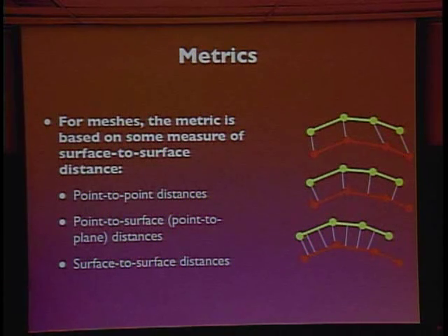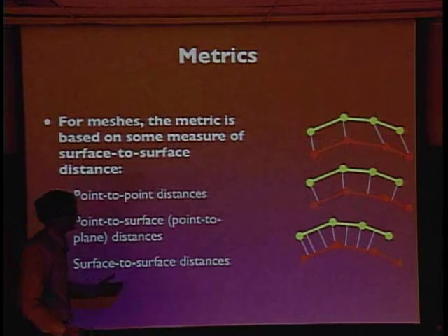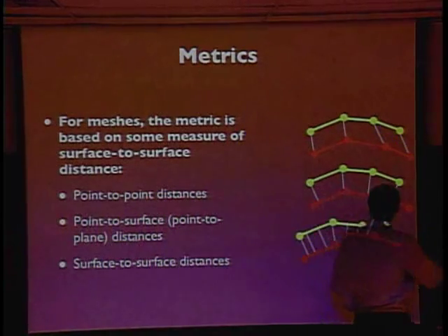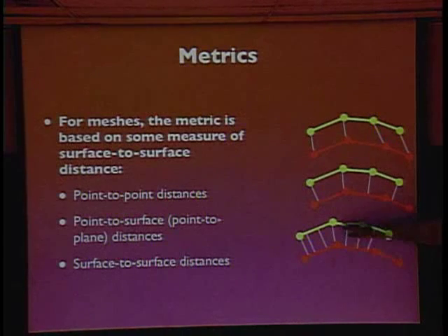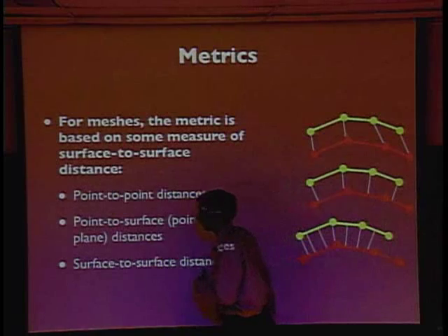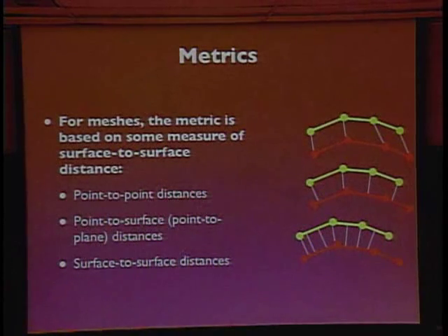So that's expensive too. This is even more expensive because you're doing all the operations you did for the other one and more, because as I've said, you're raster scanning each one of these faces and shooting more and more rays even in the middle of these faces too. So that's why the third choice, which is true surface-to-surface distances, can be very computationally expensive.